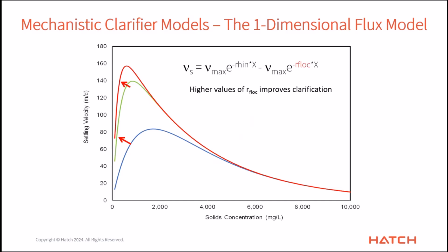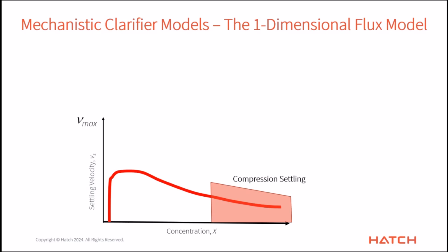And then the other parameter controls the other end. So this is the low end. So this is the top of the clarifier, and the clarification parameter setting. So I can affect just the aspects of the effluent solids concentration without really making much change in the lower half of the clarifier where the solids concentration is higher. Now, the problem we have is these two parameters actually act in different directions. And they're also very, very small numbers, 0.00051 or something like that. So they're not too terribly intuitive.